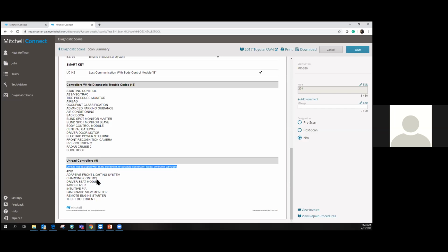So by listing them out on here, you can scroll over that list, check for any options that vehicle may or may not have, and make sure it coincides with the list you see here. And that could be your red flag, especially during a pre-scan. You can make that much more accurate of a blueprint, knowing that one of these modules is not communicating. I know this vehicle has this option. So now I can allot some more time and or money to diagnose or replace that module while I'm doing my repairs. So it's only one, that's why we will list that down there.